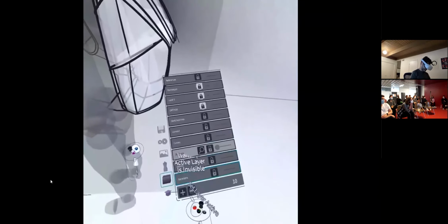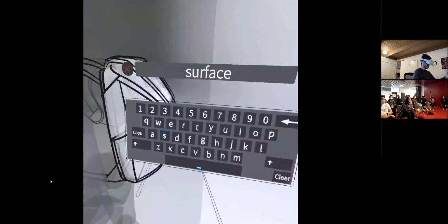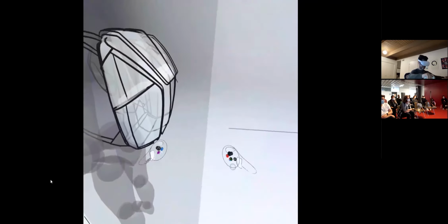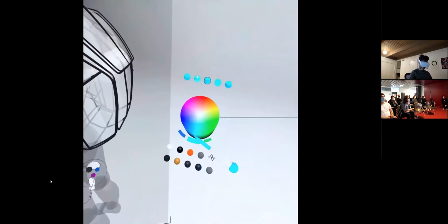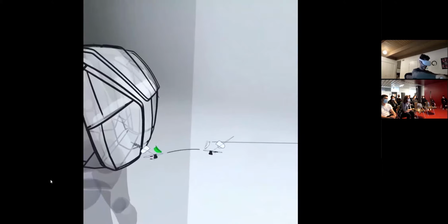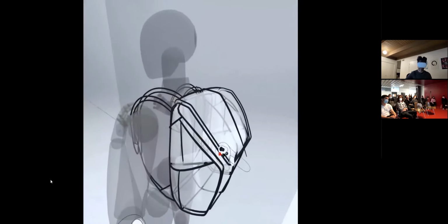I'm going to make a new surfaces layer. Now, hopefully you guys are familiar with the surface tool. This one, you can change the width, the tension, and the direction of a surface and just pull it into space, pretty unconstrained. Even above you, I would suggest just getting in there and creating a bunch of surfaces. You can also constrain them to lines, and that's what I usually do, and I'll show you here.